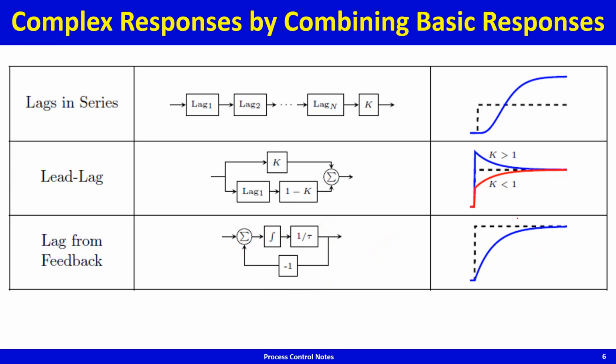So you see, we are calling lag a basic response type, but actually a much more fundamental response type is the integrator. Why do you integrate? Because rate of change, dy by dt is equal to something, some function, therefore y is equal to integral of f dt, right? So most fundamental is this integral operator.